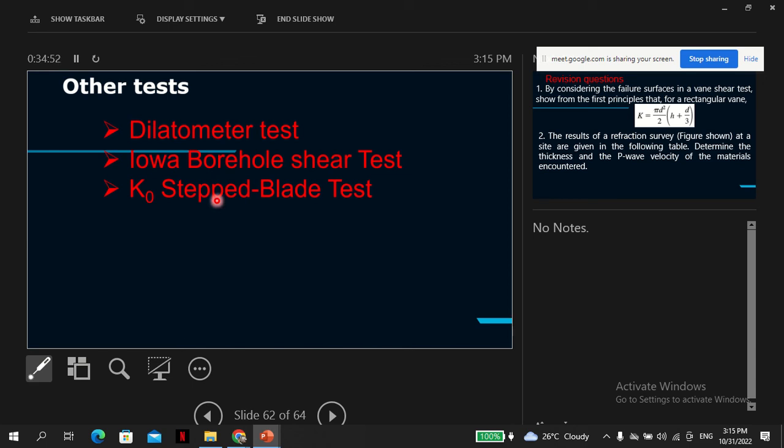Yes, so in addition to the traditional test, but for the purposes of this topic, you need to know about the CPT, the SPT, the dynamic cone penetrometer test. I'm not very much sure about the pressuremeter test. The pressuremeter test is useful, but is not very traditional. So also the traditional one is the Vane Shear test. The rest you need to be aware of because you need to know what happens outside the field. So this is why I mentioned these values.